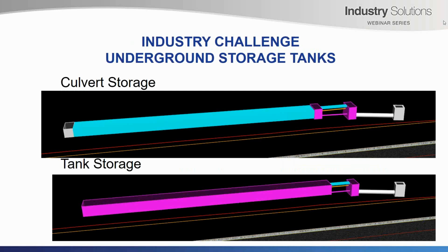Today we're going to go through a very important part of stormwater drainage. Anytime we change our natural environment, and unfortunately that usually involves putting some concrete over some very nice beautiful land, we increase the runoff, and part of our building process is to create some sort of storage so that we can reduce the peak discharges and hold back some of the water, so that we don't cause downstream flooding. That's just a very brief introduction to the whole idea of why we're doing storage on site.